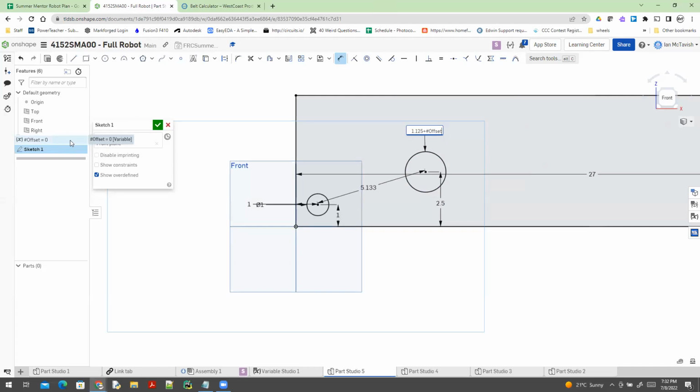But by setting that offset, when I was doing some bearing holes for different material, I literally just cut a bunch of holes and then tested the bearing and went, oh, that size fits. What's the offset? Perfect. We'll use that when we're making this material. Because if you 3D print something, then you get a different result, so it depends on how you're making it.